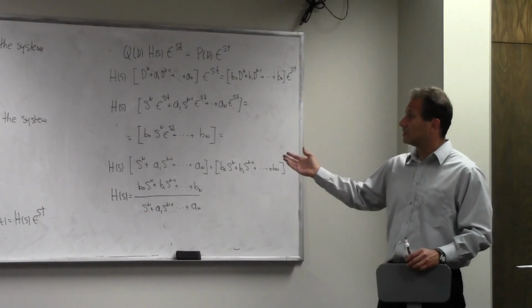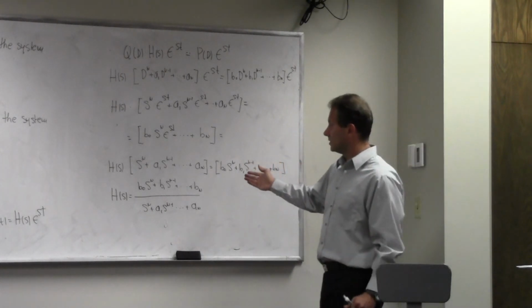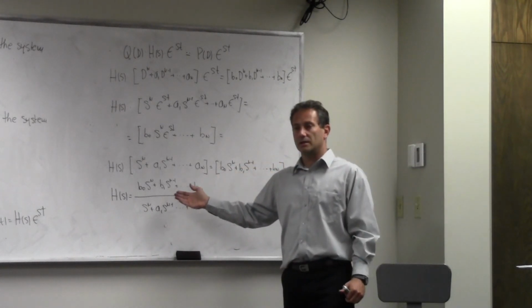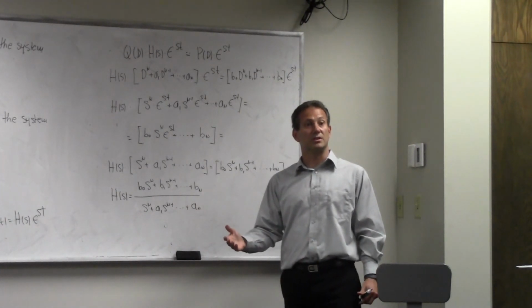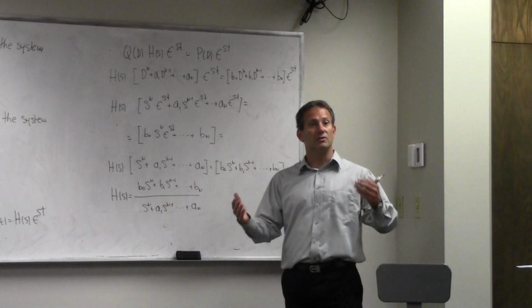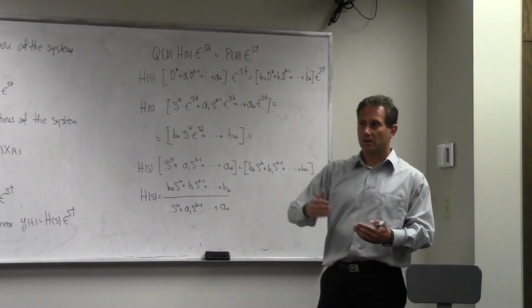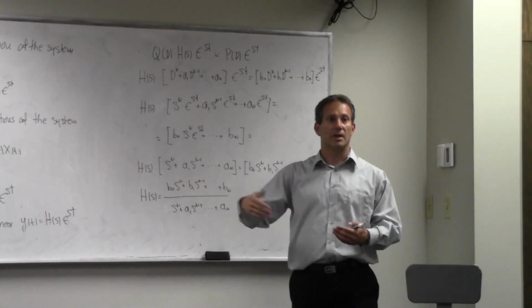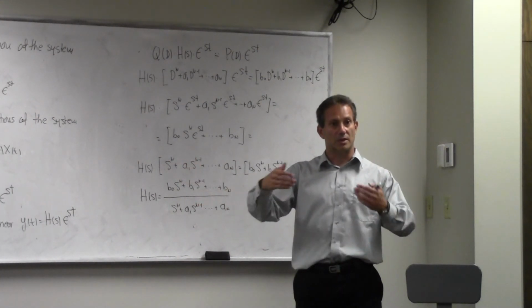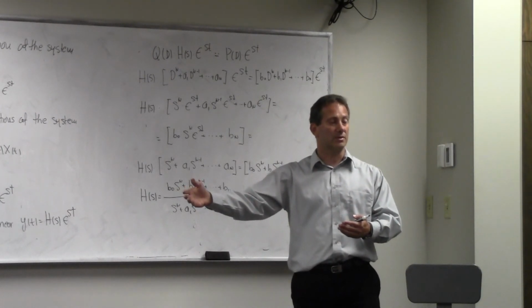So what this taught us is that if I know my differential equation, finding the response of my system to a sinusoid is a trivial task. I really don't have to do any calculation. I take the sinusoid, scale it and phase it properly, and I'm done, because I know that if I feed a sinusoid, I get a sinusoid of the same frequency.